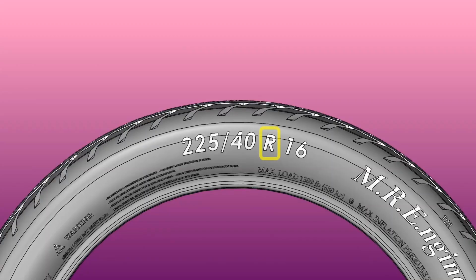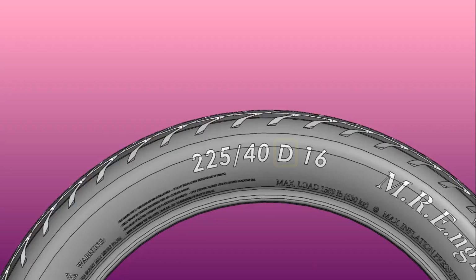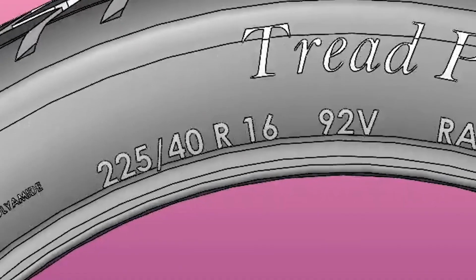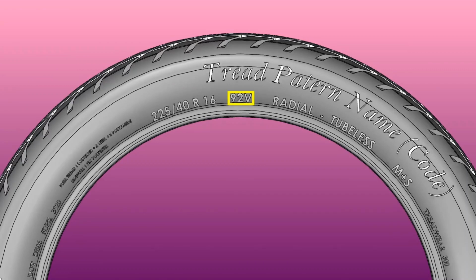The next letter indicates the type of the tire. It can be R indicating radial, or D indicating bias diagonal, or B indicating bias belted. The next 2 digits show the size of the wheel that this tire can be mounted on, and this number is in inches. After some space, you can see numbers and a letter known as the service description.